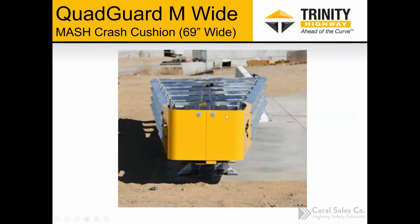There's kind of a head-on camera view, so you can see it's a straight flare on each side. In the old quad guard system, this front section used to be wider. I want to say it was close to 39 inches, that front diaphragm. This front diaphragm is right around 26 to 28 inches wide. I'd honestly have to look at a drawing to get the exact dimension, but this new quad guard M wide is narrower at the front, obviously the same 69-inch wide at the back.